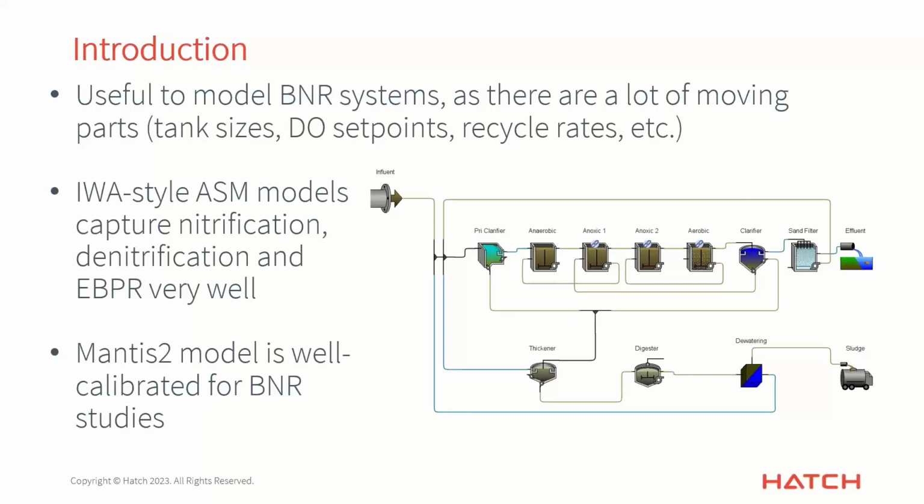The good part about all of this is the IWA style ASM models that you see in GPS-X, that were based upon that ASM1, ASM2D type of approach from 30 years ago. They capture nitrification, denitrification, and EBPR or BioP processes really well.